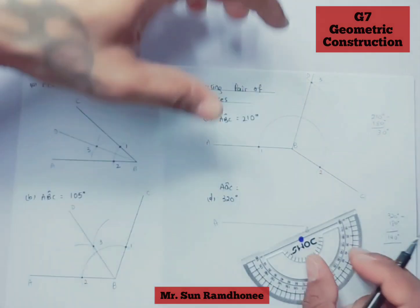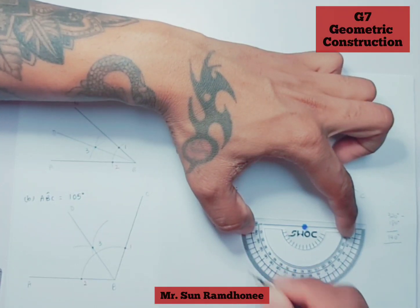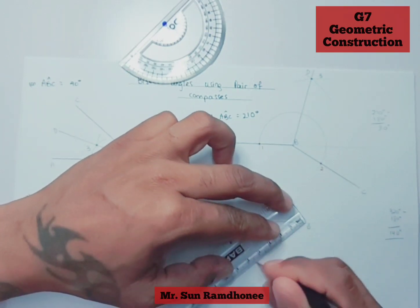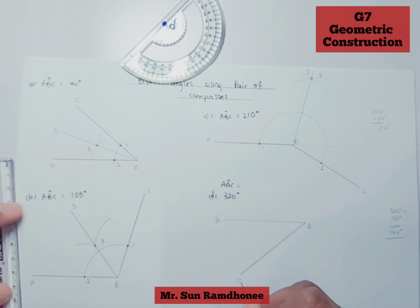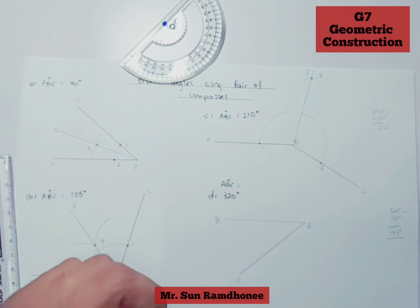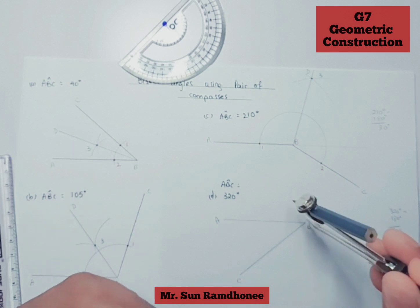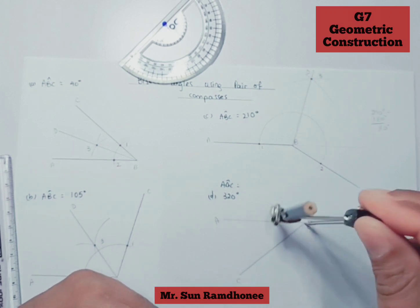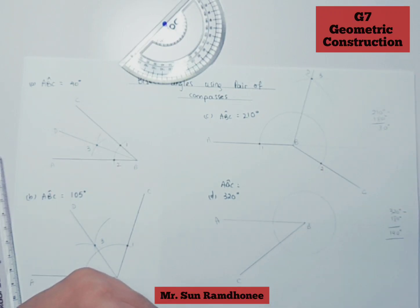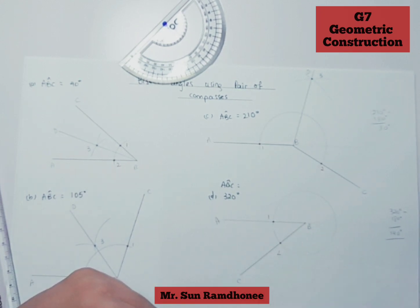So from here we're going to measure up to 140 degrees, which is here. We're going to draw the line from point B to here, and this is point C, and all of this is 320. I use my compass to measure the width of my finger, and then I place it on point B, and then I draw this arc. It will touch 2 points on line AB and BC, 1 and 2.